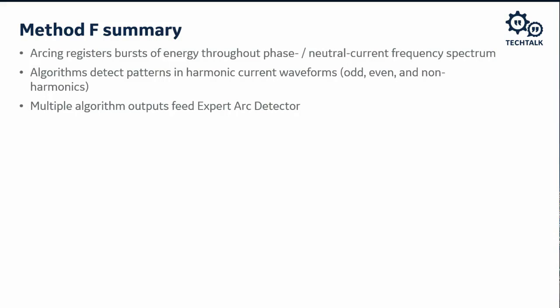The basis for down conductor detection is event dependent. Differentiation between an intermittent arcing intact conductor and an arcing down conductor is determined by looking at the patterns in the load current at the beginning of the fault. User settings determine what constitutes a loss of load or an overcurrent condition. When a conductor breaks, generally there is a loss of load, or an overcurrent condition when a phase hits another phase. This gives an indication that the conductor broke. The detection method looks for arcing to determine whether the conductor has fallen to the ground or hit a grounded object.